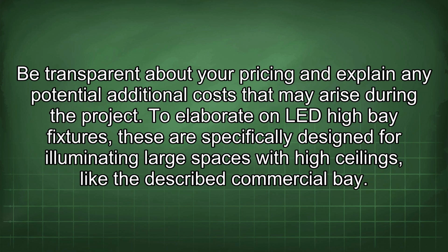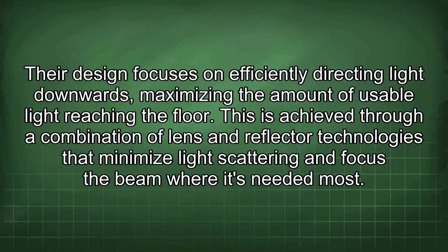To elaborate on LED high bay fixtures, these are specifically designed for illuminating large spaces with high ceilings, like the described commercial bay. Their design focuses on efficiently directing light downwards, maximizing the amount of usable light reaching the floor. This is achieved through a combination of lens and reflector technologies that minimize light scattering and focus the beam where it's needed most.